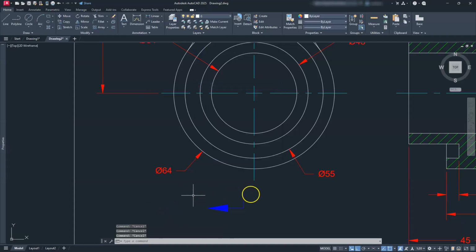All right, let's go ahead and move this. So I'm just going to select it. Go to move, enter, go from this endpoint, place it right on that endpoint there. I thought I had it on the right layer. Let me go ahead and select here and put it on the section layer. Oh, I actually changed my current layer. Okay, there we go.